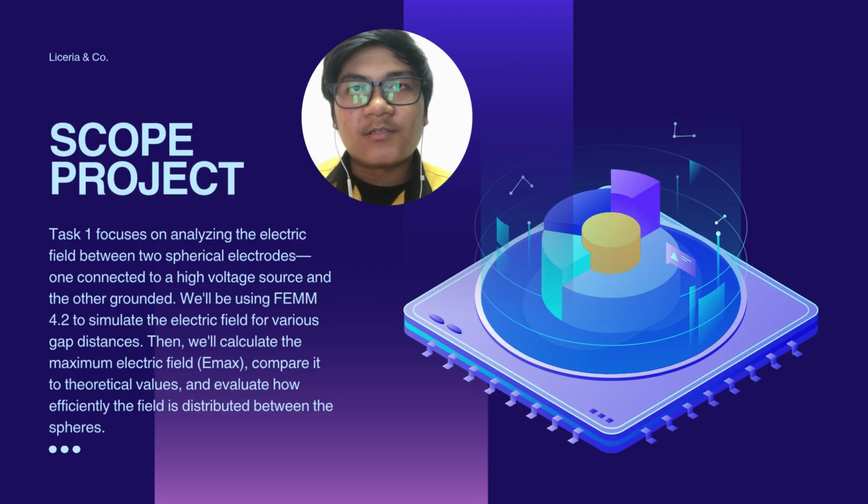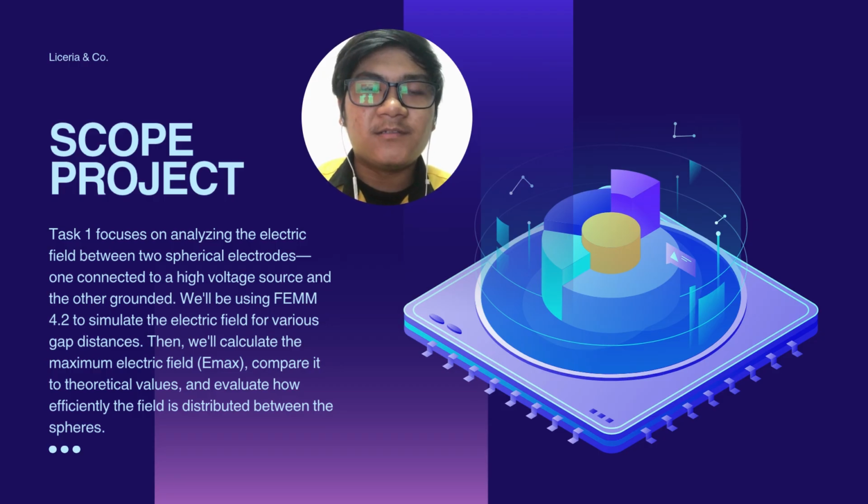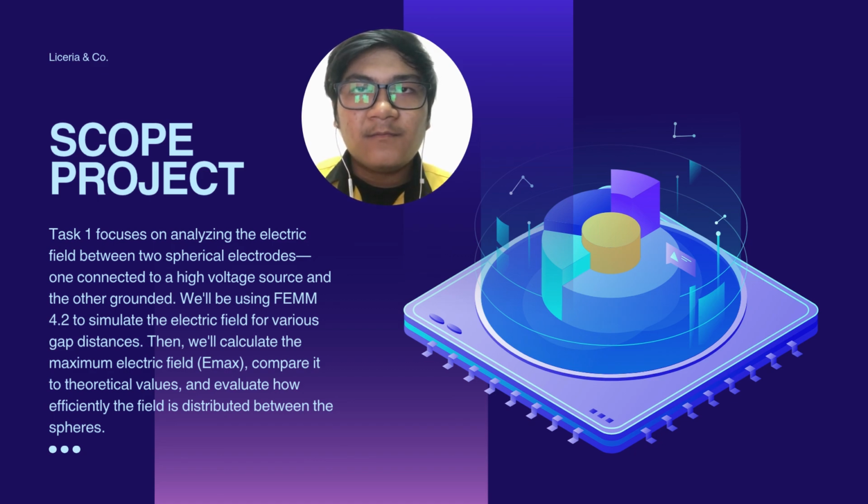So the next one is the project scope. Task 1 focuses on analyzing the electric field between two spherical electrodes, one connected to the high voltage source and the other one grounded. We'll be using the FEMM 4.2 software to simulate the electric field for various gap distances. Then we'll calculate the maximum electric field, or Emax, compare it with the theoretical values, and evaluate how efficiently the electric field is distributed between the spheres.